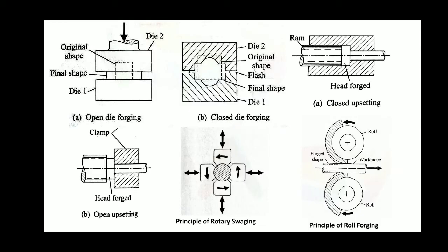So this figure shows the different types of forging processes. We already know that in the forging process we use some localized compressive force, and we manipulate the shape and size, or you can say the cross section, of that particular material. And that final product becomes the forged part. We already know that the required compressive force is generally applied by different types of hammers, maybe hand tools, hammers, power hammers, etc.